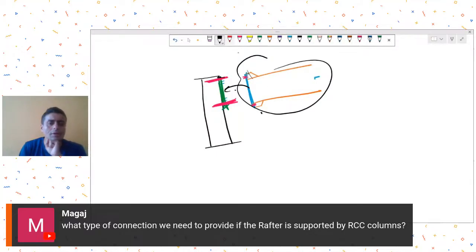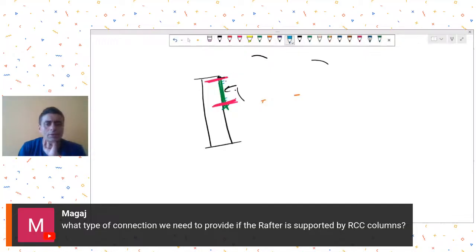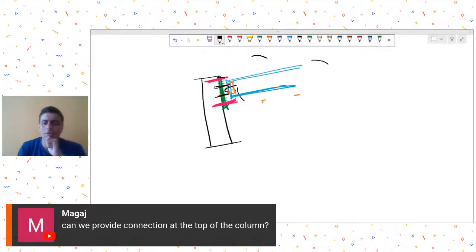If you wanted to have a shear connection, it will be simple. You could just have this plate pre-welded to the column face, and then you could bring your beam, have cleats over here, and then those cleats could be welded on site. If you wanted bolting on site, you will either need anchor fasteners, or you could have anchor bolts pre-cast in your concrete, and then you could come up with the connection. So whatever strategy you want to come up with for the connection, you could do that.